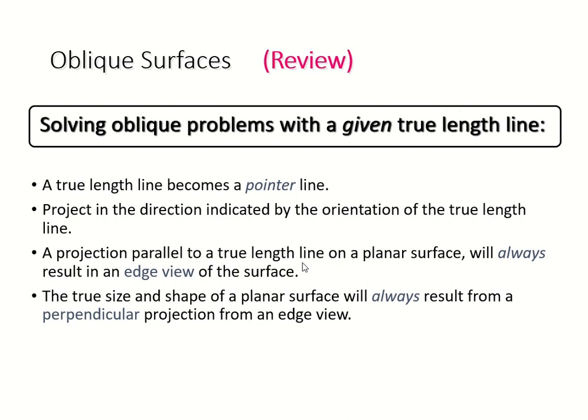Remember the previous program we did on a planar surface is going to give you the edge view, the primary auxiliary. And then the true size and shape of a planar surface is going to result from a perpendicular projection from that edge view. Just recalling what we did, okay?